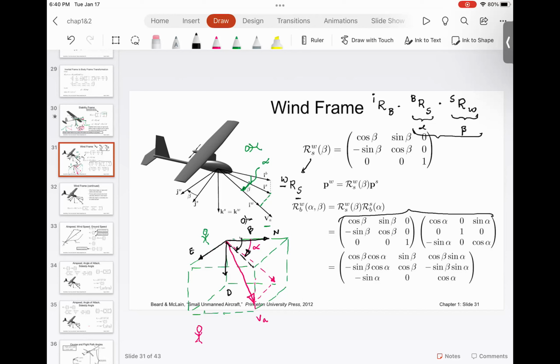So when you rotate like this, this is the positive angle of attack. When you have a positive angle of attack, you measure lift. But this positive rotation that is causing lift is actually negative in our sign convention because of the frame orientations. To make sure that this rotation is causing lift, we have to have minus alpha.